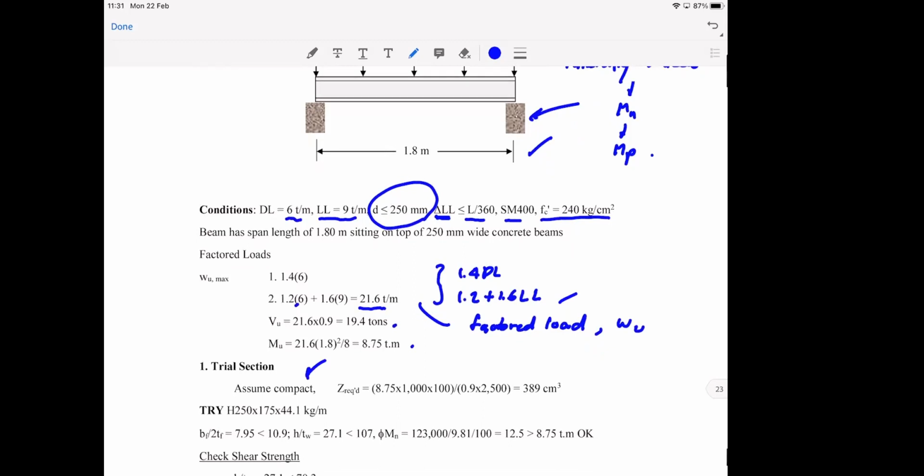And from this Mp, which is equal to Fy multiplied by plastic section modulus, and then multiplied by the phi, okay? That becomes your... no, I shouldn't apply phi yet, because that would be the nominal moment, okay? That would be the design moment, and we have the phi Mn, which is equal to phi Mp. It should be greater than Mu.